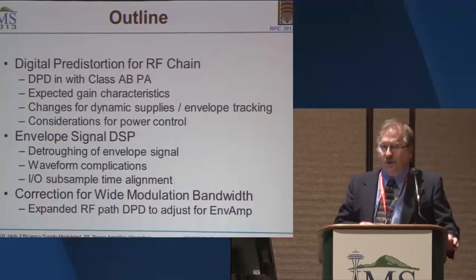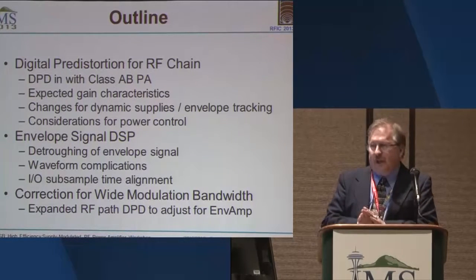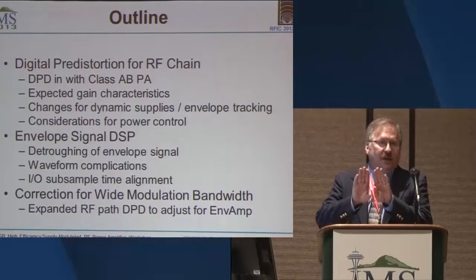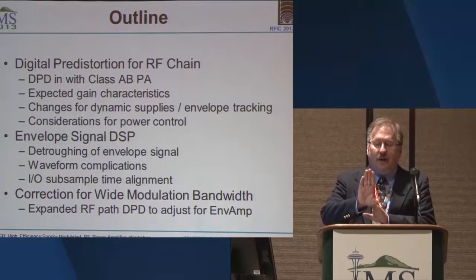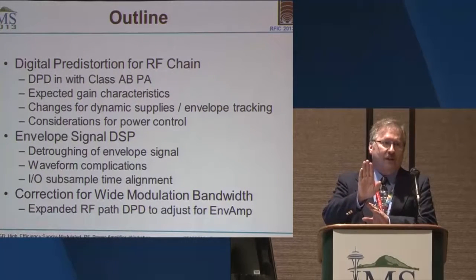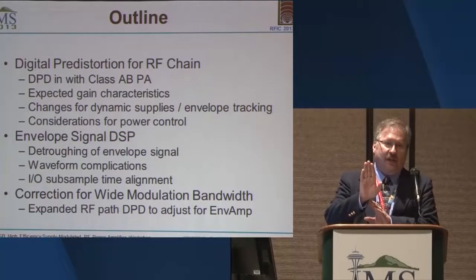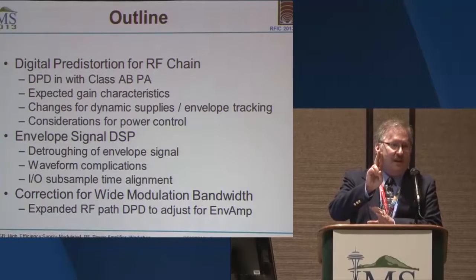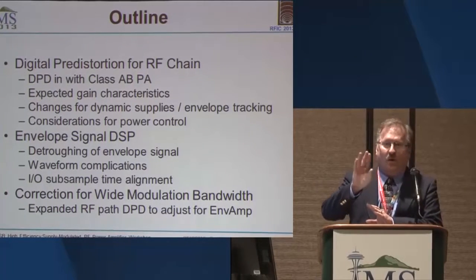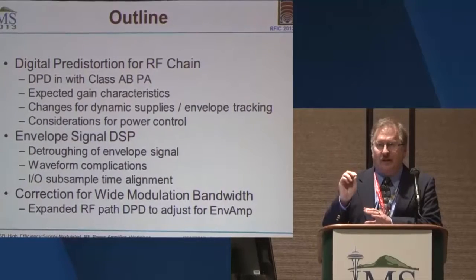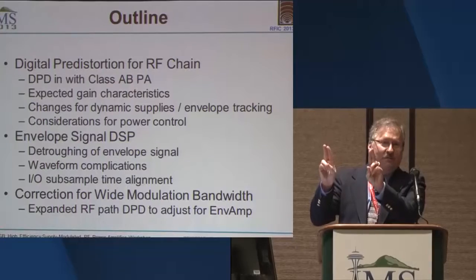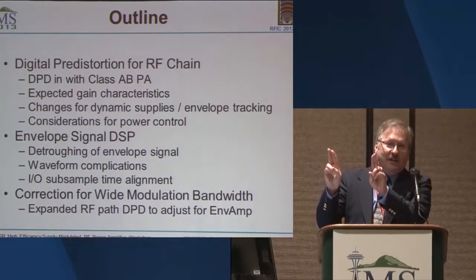As Professor Larson was just saying, our life is going to get more challenging moving forward. In addition to the bandwidths getting wider, designing a PA just for one particular bandwidth is something we're starting to see those days wane. LTE is a case where at times we're going to have just a few RBs activated on one side of the band or maybe some on the other side, and then they'll come up with LTE-A, which lets them do RBs on either side of the band simultaneously.